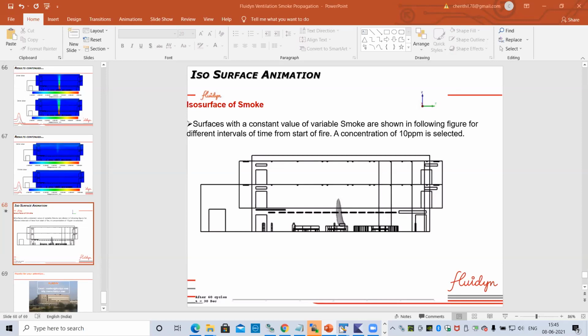But when you are doing fire-related smoke propagation, these things are often not so important, because fire is dominated by very high convection due to buoyancy. There the gas assumption is more than sufficient to see where the smoke is going. But for other cases where you have particles in a cool atmosphere, like room temperature, you cannot use a Newtonian description or model it like a species. You have to model them as particles and see how they drift.